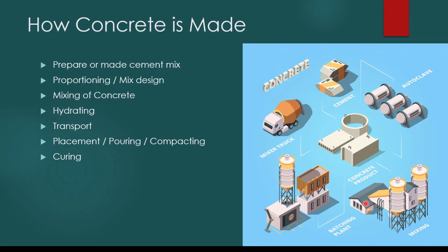We select the mix proportion, how much cement, how much aggregate. Likewise, you select the mix proportion. Once you have selected the mix proportions, we also fix the target strength based on the relevant standard and the grade you use. Then we do the trial mixes. Now we want to check whether the prepared mix design achieves the strength.